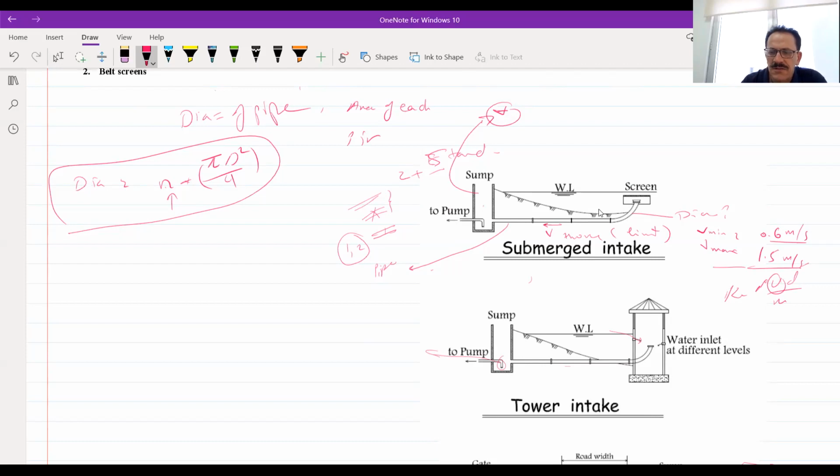Now, this is the second thing. The third thing is the emergency case. In an emergency, it means we allow turbulence, but only for a while, for a couple of seconds or minutes. This is in case one of the pipes is broken. So what should we do? We should send emergency flow and cover that one. In that case there is also a V, called the emergency or maximum peak velocity. It should be less than 2.5 meter per second.